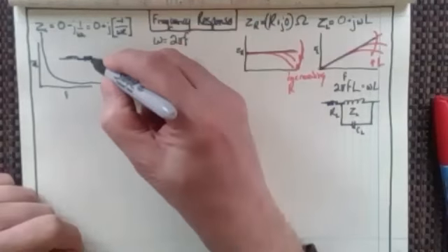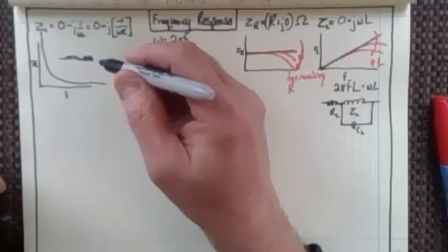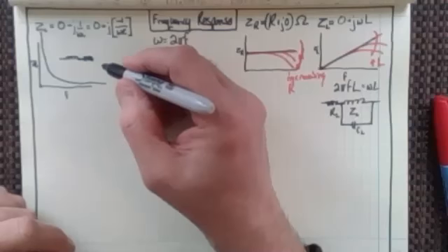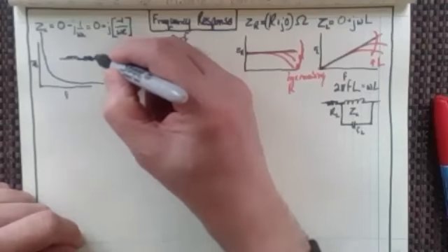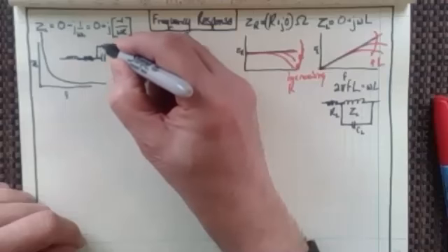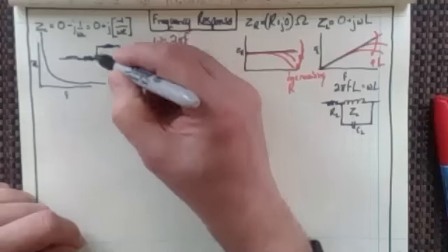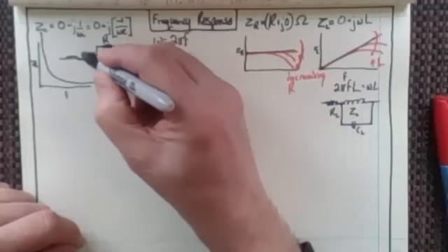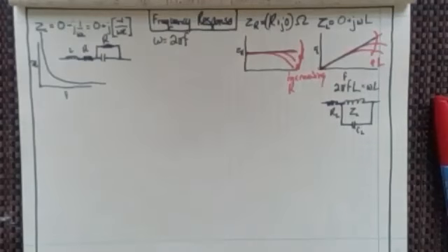So there's going to be an inherent resistivity associated with that. And then we have the capacitor. And then in parallel with the capacitor, we also have a resistance for the capacitor. So I've got a resistance here, inductance here, and that's what the circuit really looks like.